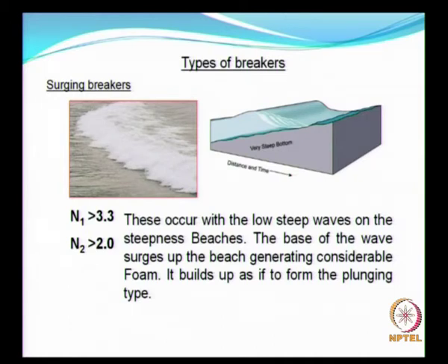Then surging type of breakers: these occur with the lower steepness waves on very steep beaches, and the base of the wave tries to surge up the beach, generating a considerable amount of foam, as if it is going to form a plunging type of breaker.